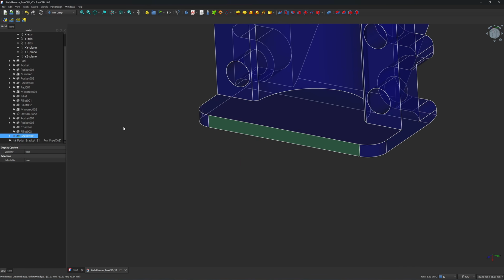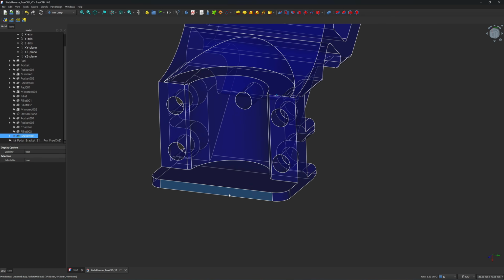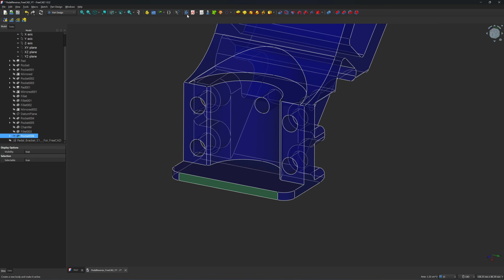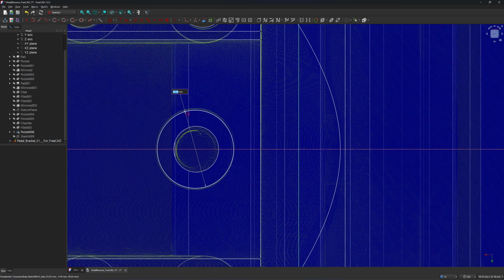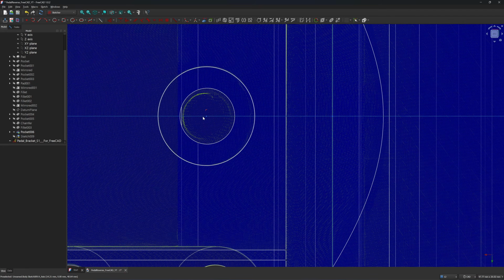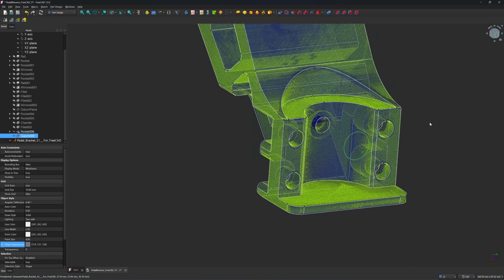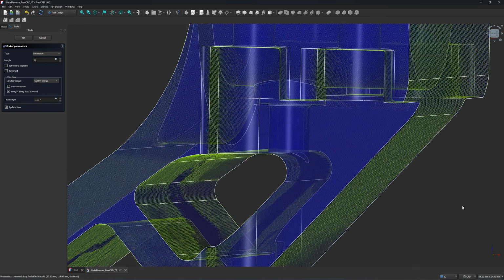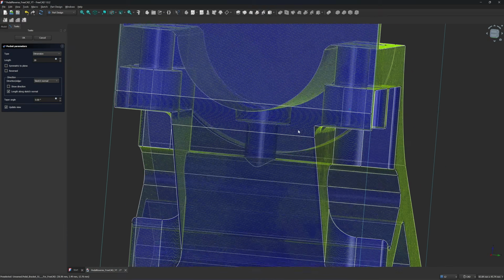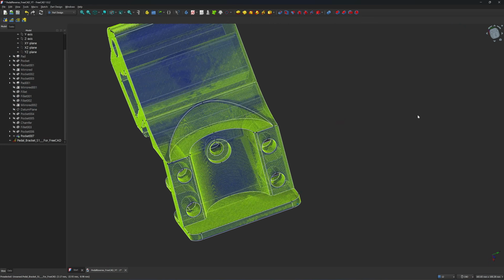Click on this face. Because there is no flat face here, it's a curve, you need to choose the flat face. To create a sketch, turn on the point cloud, draw a circle. Okay, just trace it. If it's not in the center, you can move it. Likely that is in this position. Close the sketch. There is too much. 25. Yeah, 28 is perfect, touching the bottom of the hole. Click on OK. Now we have a counter bore hole for the screw.